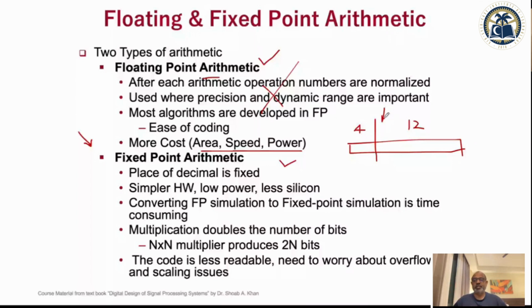And that is not easy, because a lot of simulations have to happen before you understand where you should place your decimal point. Fixing the place of the decimal will definitely make your hardware very simple and very low power. It'll take less silicon, because though you are doing floating point arithmetic, fixing the decimal converts it into just integer multiplication and integer addition, and that is going to be very helpful in designing an architecture.